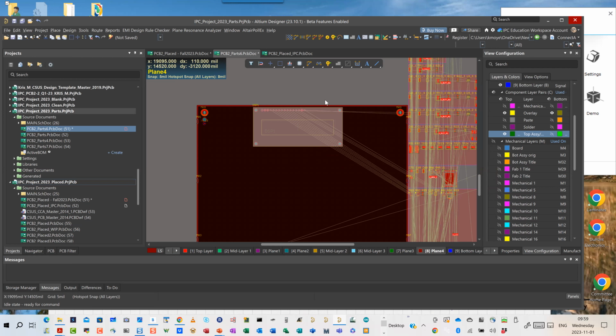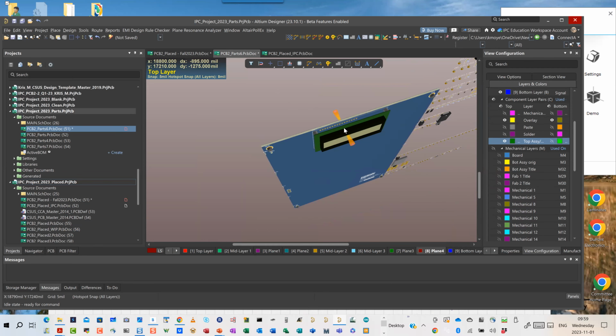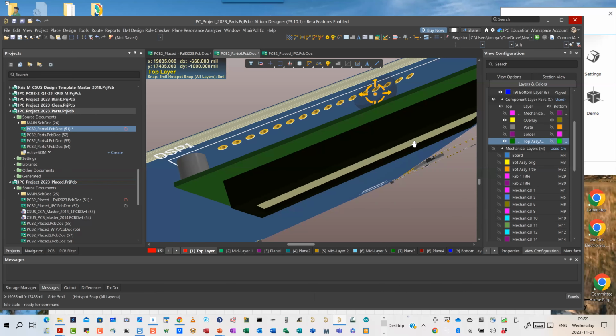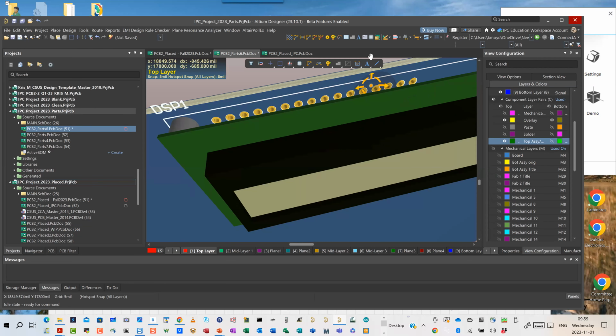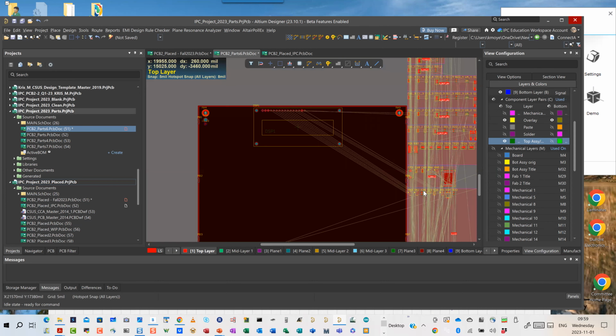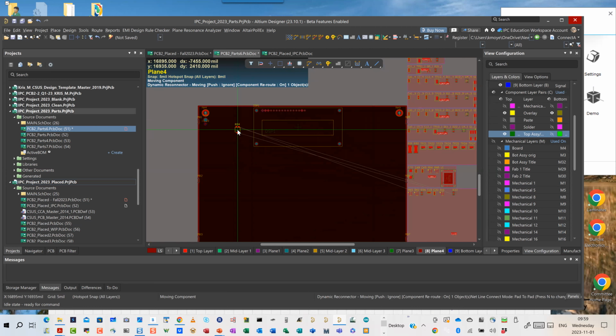Additionally, because this is a part on a standoff, we saw the picture of this. If I look at this in 3 dimensions right here, you'll notice there's a standoff, so there's some amount of z-axis height difference right there. So although it doesn't seem like it, I can go ahead and do things like adding everything except a potentiometer. So a potentiometer part right here that's in that module, that we're going to use for controlling like contrast or brightness adjustment. Obviously for human interface, that can't be stuck underneath, so I'm going to stick that outside.